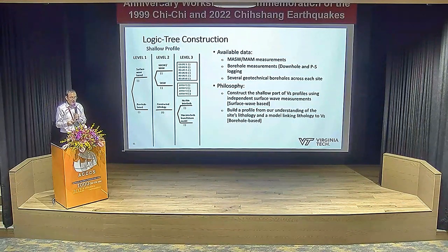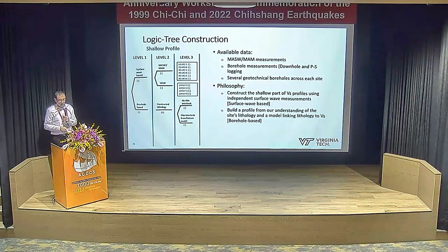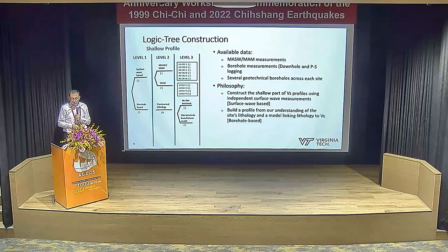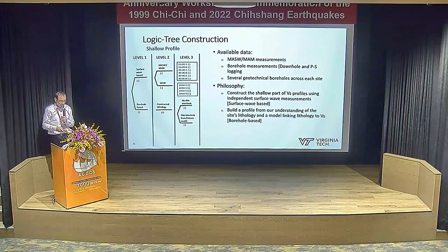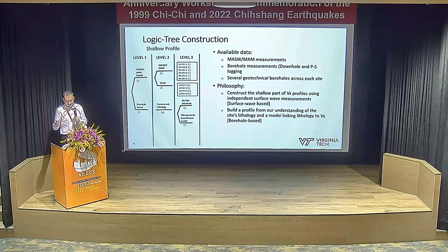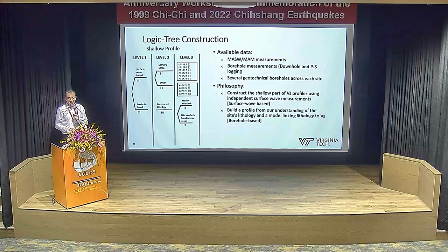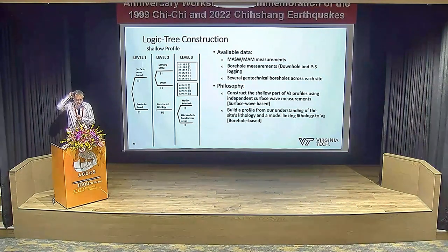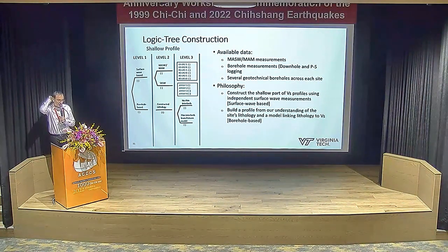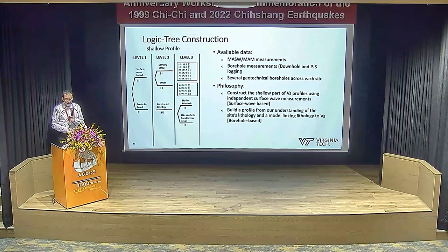So going systematically through these contributors, we start with a shallow profile. The data that we have available were measurements using MASW and microtremor array measurements, as well as, I should have said that, otherwise I'm going to get killed over the next week. We also had SASW measurements, which are stated here, that were done by Professor Stokoe. And then we had borehole measurements, both downhole and PS logging at the site.